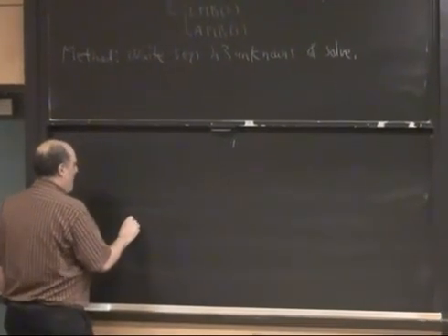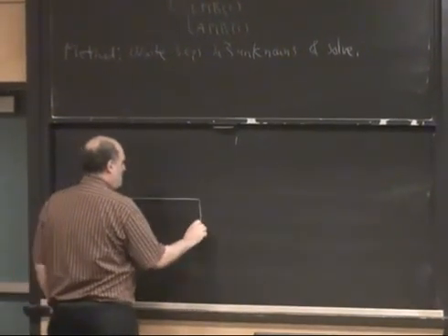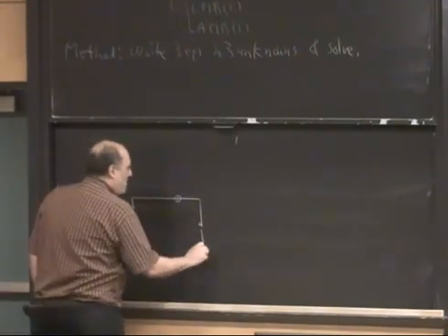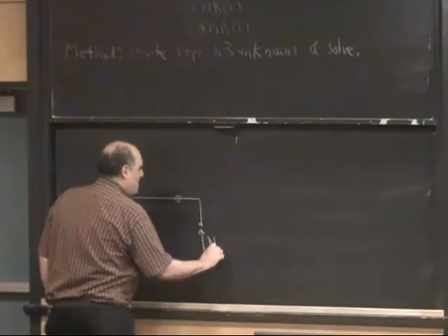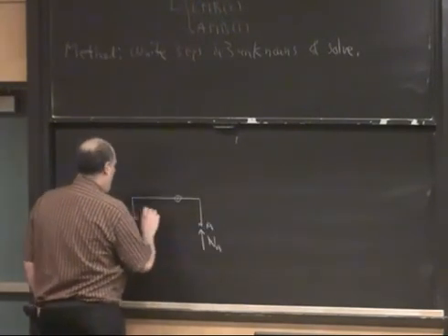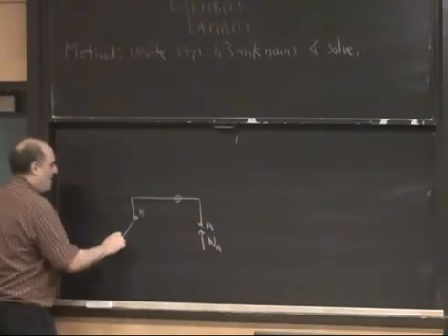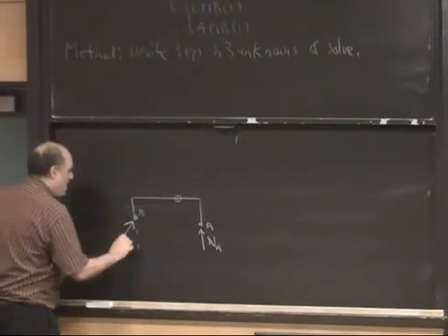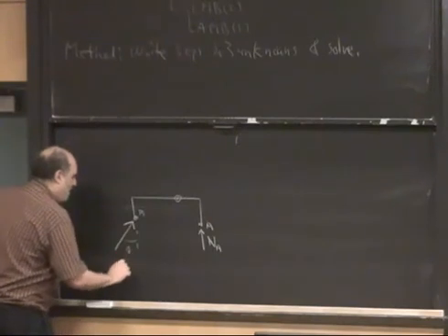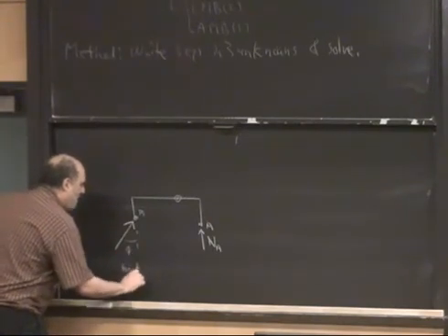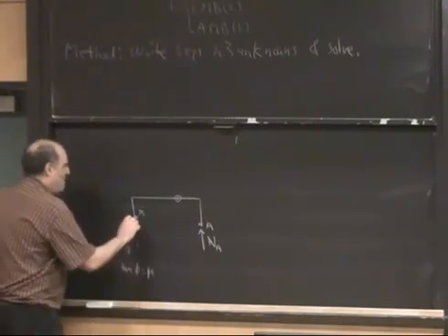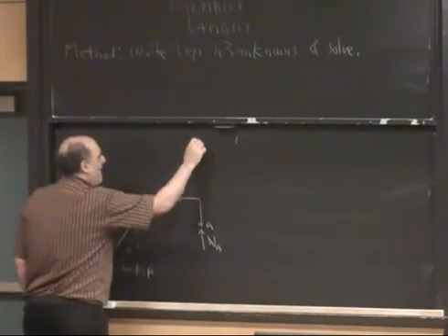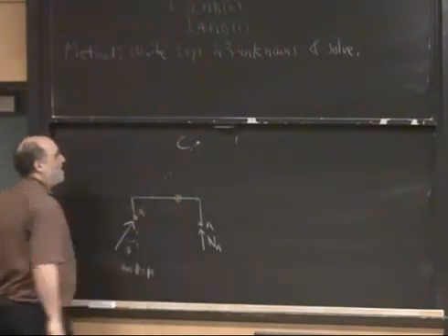So let's look at this free body diagram. We have an unknown force here, but we know its direction. And we have a force here, and we know its direction. It's in the direction of phi, where tan phi is equal to mu. And since we know its direction, we can do this geometry problem, and we can find this point here, and we can use that point, C.